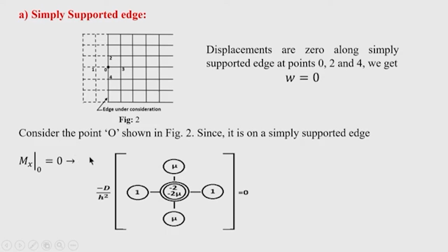Now, imposing this condition, if I place these grids, one point is on the imaginary grid point and the other is on the real grid point. So, this is the image point and this is the imaginary point. Now, the deflection of the imaginary point is meaningless, so we have to express the deflection of point 1, that is on the imaginary grid, in terms of the corresponding deflection of the image point. The image point is 3.